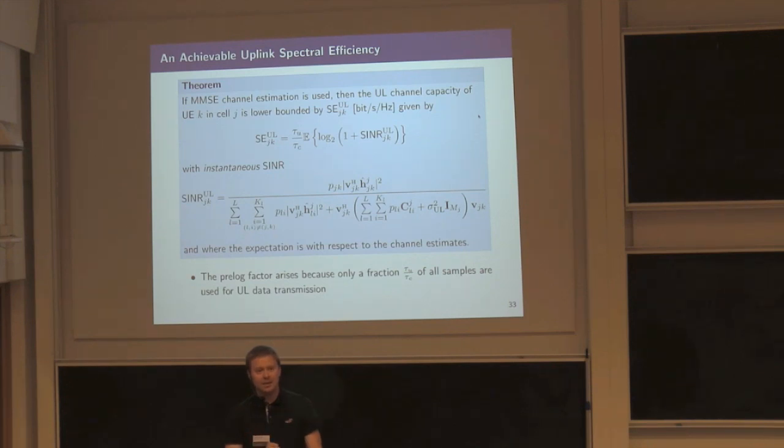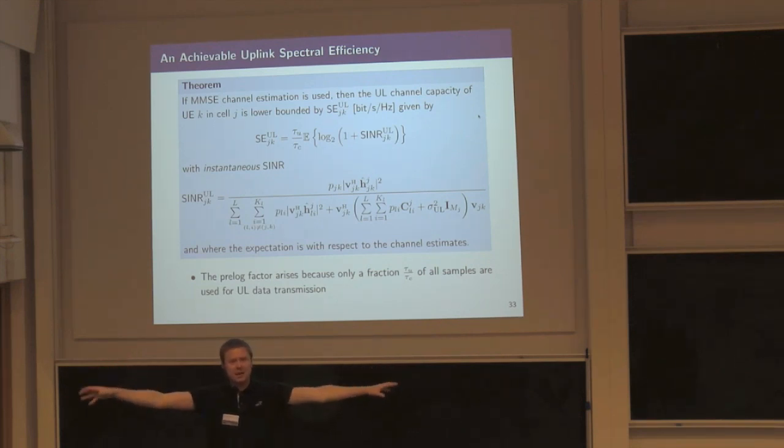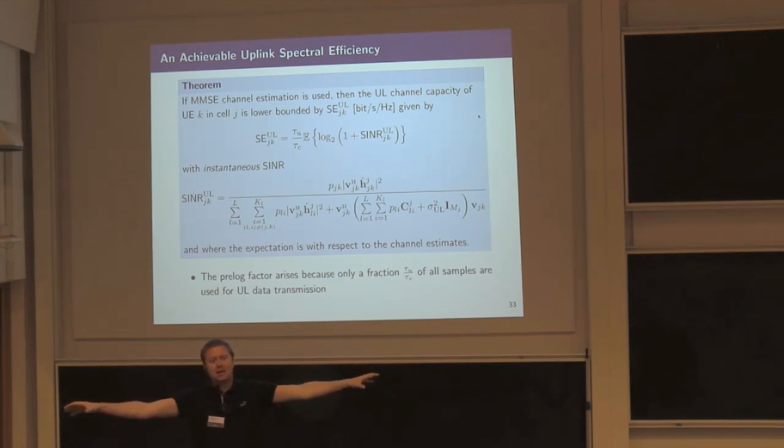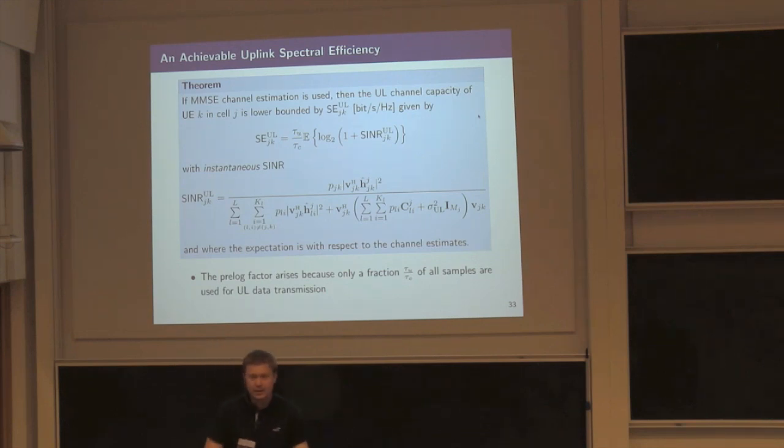You essentially need these 20 strong eigenvalues, that number needs to be a large number before the channels actually start to look orthogonal. While if the users are in very different subspaces, then you get this favorable propagation much faster. And that is something that we will see as important also when we go forward here.